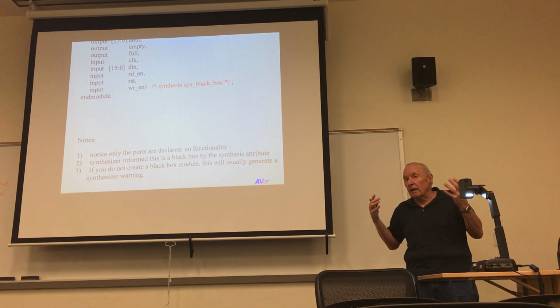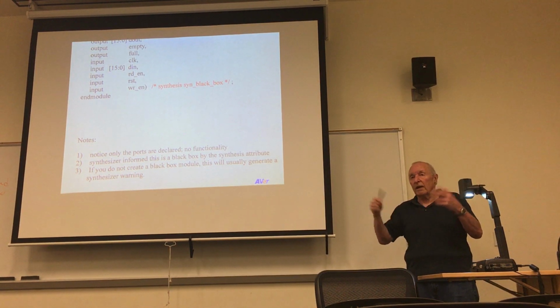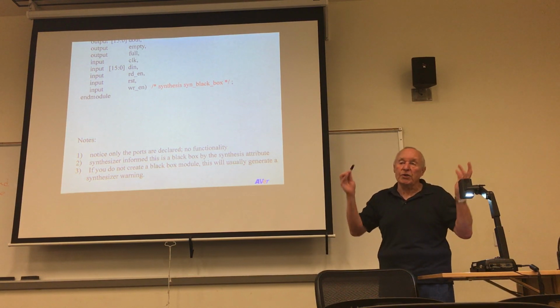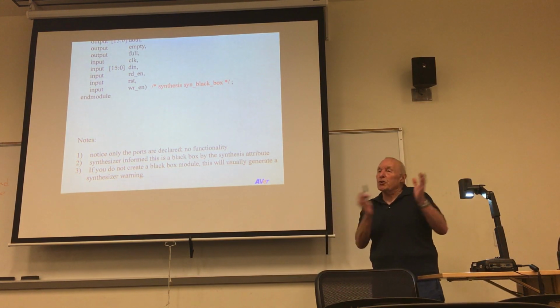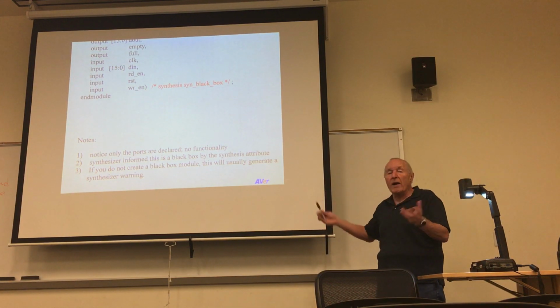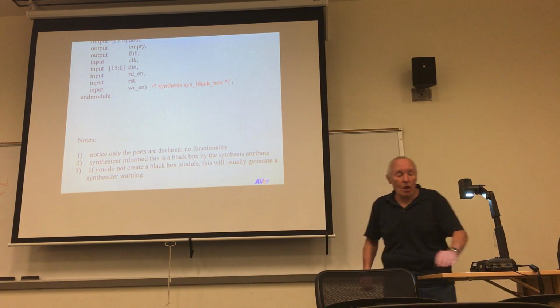If it doesn't, then place and route is obviously going to fail. And place and route will issue an error and say, you got a black box module and I don't have a clue as to what to do about it because you didn't provide that .ngc file, that EDIF file, or whatever that the core generator produced. Okay?